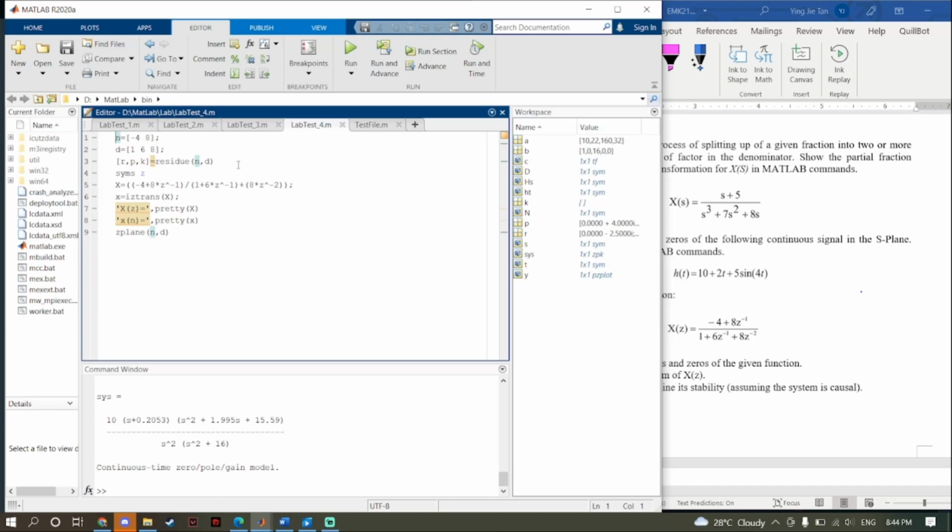Put in, and then we put this one to get the poles and zeros for the system to remember it, and later it will plot out for us. And this is our equation and syntax, which means we are in Z domain, and later it will plot out a Z plane for us. And this is the command to plot a Z plane, and we can run the system.